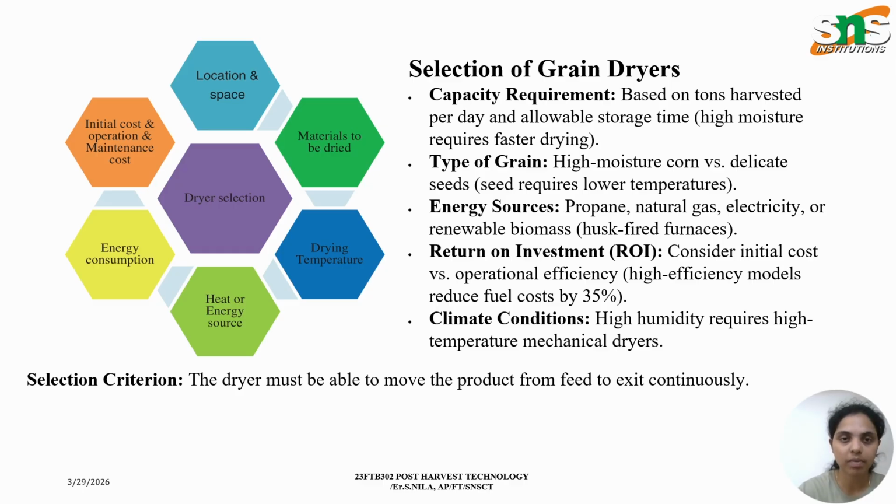And return on investment. High efficiency dryers can reduce fuel costs by up to 35%. And the climate conditions. In high humidity areas, high temperature mechanical dryers are preferred. So these are the main selection criteria for the dryers. Okay.